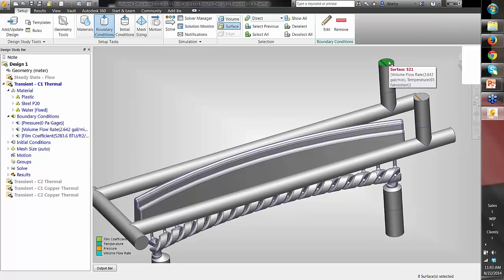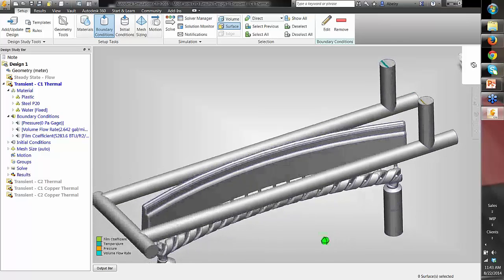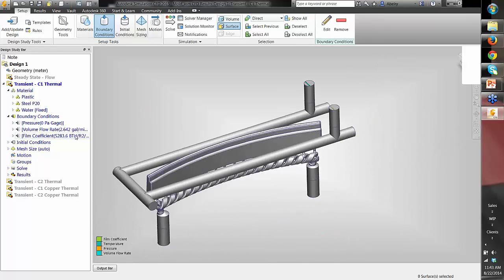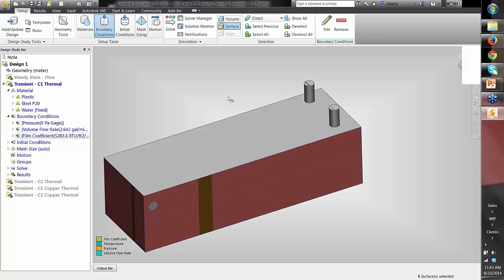It will solve for the Reynolds number, but more importantly, you're going to get all the local internal flow characteristics through the pipe and understand the interaction of the fluid at the wall, and that's where all that heat is being extracted. Then for the thermal side of the equation, we're going to do the same thing as you would inside Moldflow, which is allow heat to leave through the steel to the ambient shop environment.